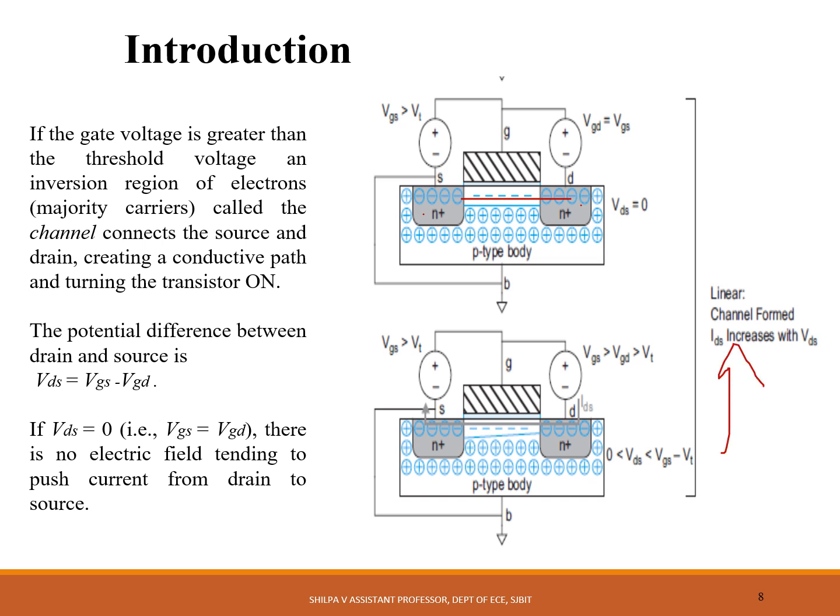If VDS becomes sufficiently large, if VGS is large enough, the channel is no longer inverted near the drain and becomes pinched off. This is called the pinch-off region. However, conduction still continues by the drift of electrons under the influence of the positive drain voltage. As electrons reach the end of the channel, they are injected into the depletion region near the drain and accelerated towards the drain.